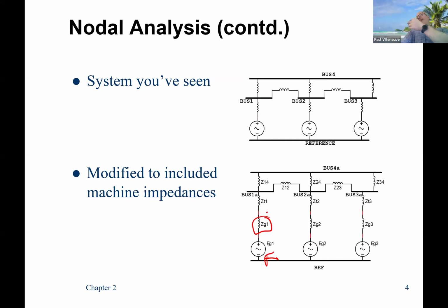So you're right that it does have an inductance or an internal inductance, but the reason why we actually put that in there is because we have to limit the amount of energy out of the power supply, right? So under short circuit conditions, you're not putting out an infinite amount of amps. You're putting out maybe 200,000 amps or 50,000 amps, whatever it works out to be. And that impedance is proportional or equivalent to whatever it needs to be to knock that value down.